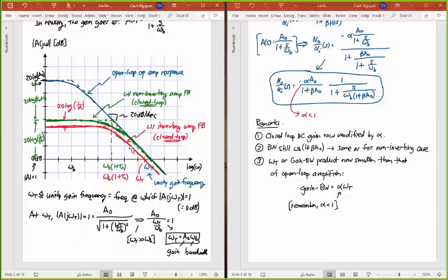And so what does this tell you? It says that the non-inverting amplifier, if you just wanted sheer gain, bandwidth performance, non-inverting amplifier is the better way to go. Okay, inverting amplifier is not as good an amplifier as a non-inverting amplifier. And we've just proven that with just this understanding, this sort of brute force and intuitive analysis of the feedback circuit. The question here, is a smaller gain bandwidth product a sign of some kind of energy loss through this circuit? Yes, it is. So just putting the resistor up front, that resistor R1, actually impacts a few things for you. You already see how it impacts because it creates that alpha term here.